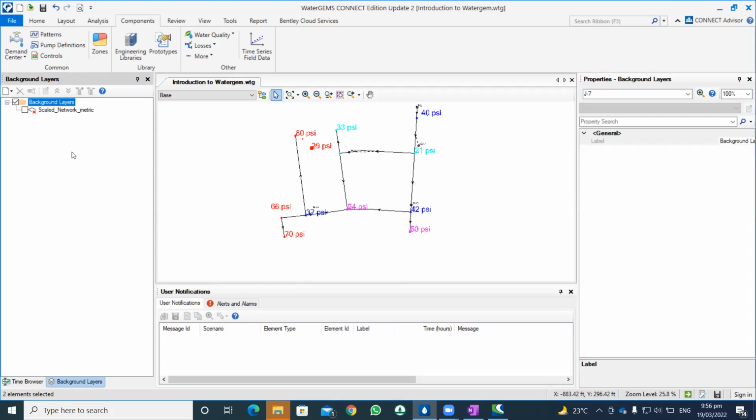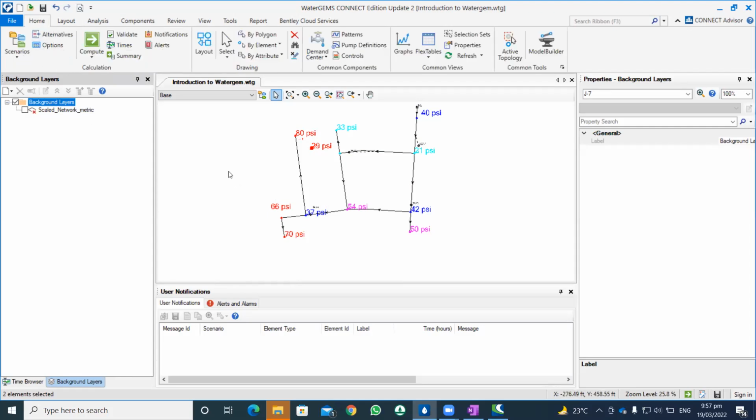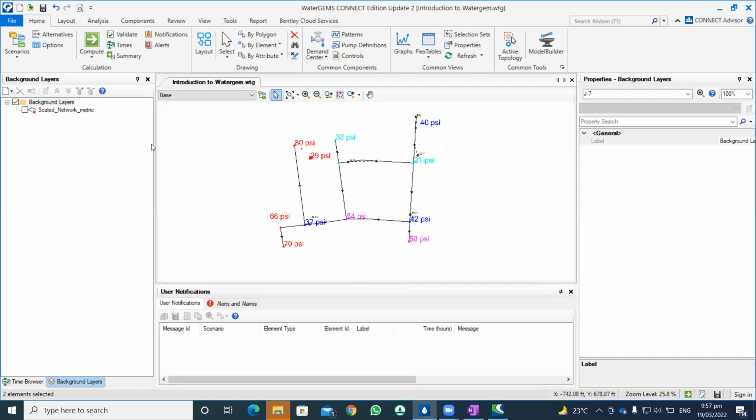Going to each junction, creating a different scenario and assigning a fire demand, for example for 100 or 110 junctions, is very difficult to analyze one by one. So I will show you how to do that automatically for the specific junctions involved in your water supply network.